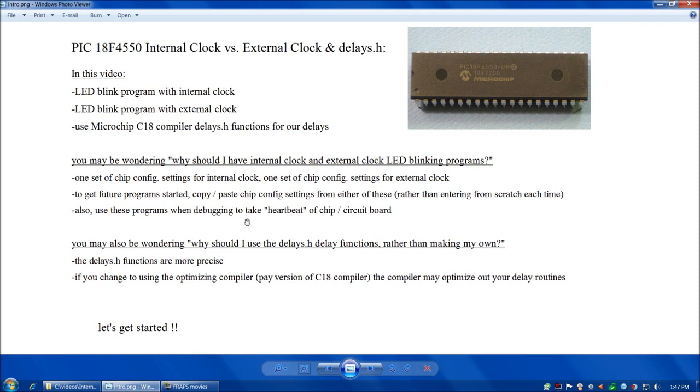Well, the best first thing to do to make sure the chip is at least getting the power that it needs, the ground that it needs, that it's able to read the oscillator and do basic functions, is you can load one of the blink programs into your chip. Of course, you'll have to put a LED on your board if you don't already have one, but load that in there. Just make sure you can get a LED blinking, because maybe there's something fundamental that the chip isn't even getting, and then once you know you have that, you can debug from there.